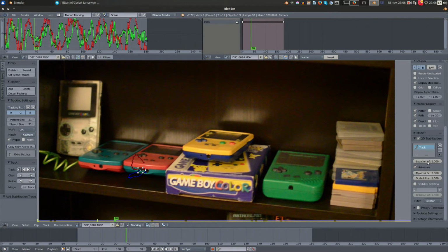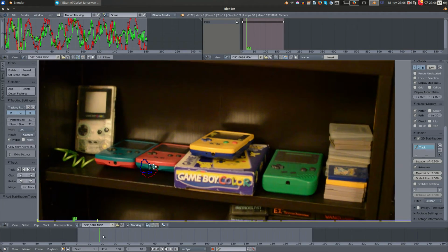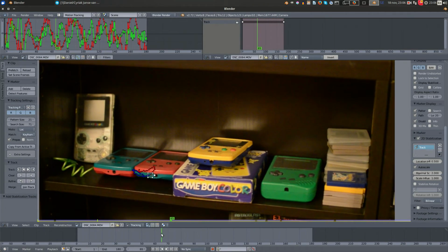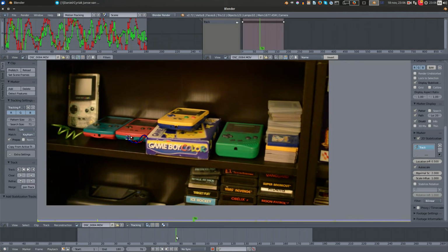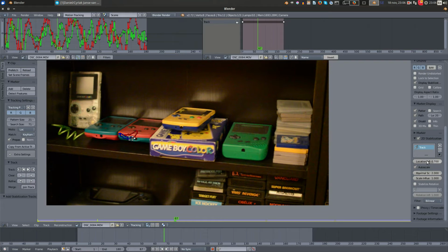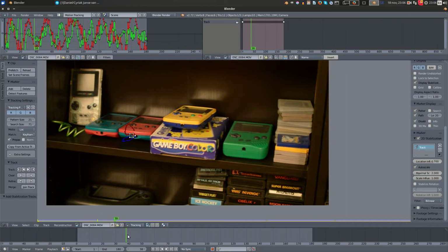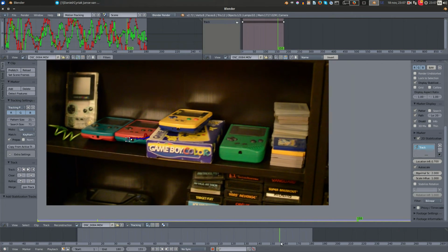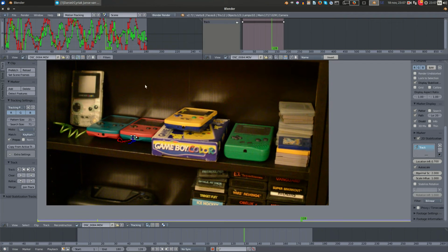So to solve this, you change the location influence value, let's say to 0.5, to reinsert some of the shakiness, but we have successfully removed half of it, but this is still a little bit too shaky, so let's try 0.7. And this is all individual, you just find what looks best for you. Okay, so now we have a bit of camera wobble, and we have removed most of the stationary wobble.